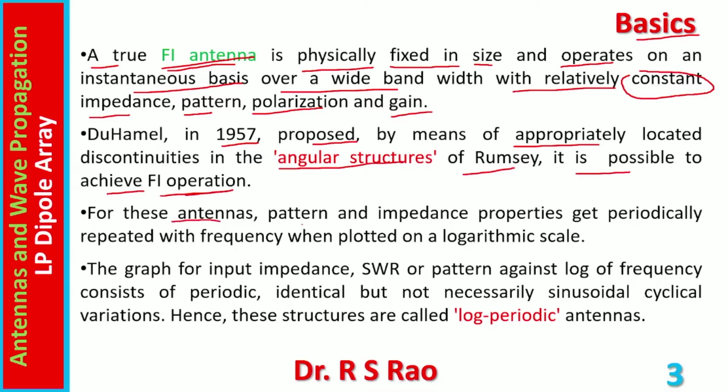For these antennas, pattern and impedance properties get periodically repeated with the frequency when plotted on a logarithmic scale. The basic principle of frequency independent antennas is Rumsey's. Duhamel suggested an amendment in which he allowed discontinuities in the angular structures of Rumsey.